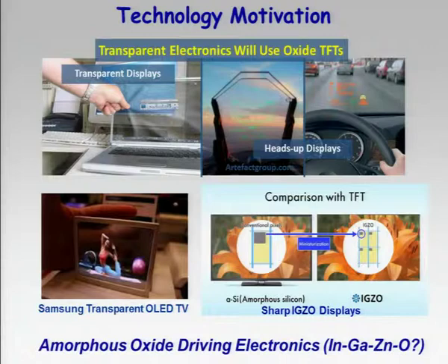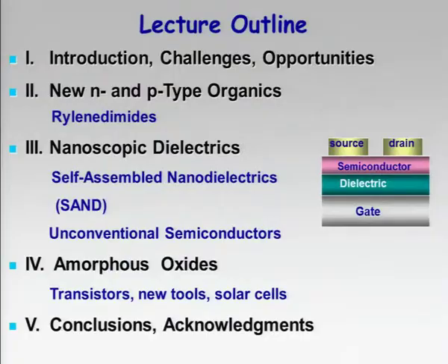This is now one of the interesting materials that is sort of coming on the scene, indium gallium zinc oxide, IGZO. And this is just from the Sharp website, so they've perfected this, but much better mobilities than amorphous silicon and optically transparent. So it takes up much less real estate on the display. And this is just Sharp showing you, here's amorphous silicon, and here's IGZO, how you can miniaturize the pixel. So that's really exciting.